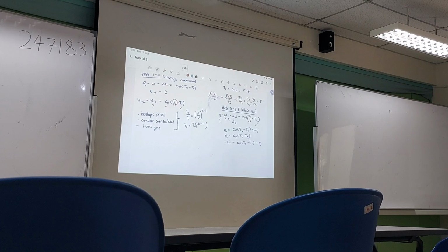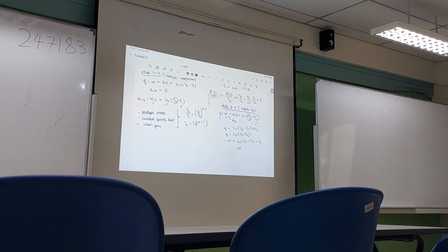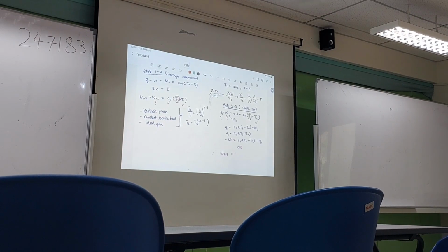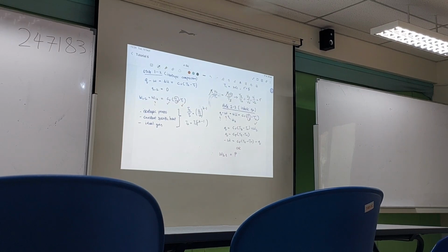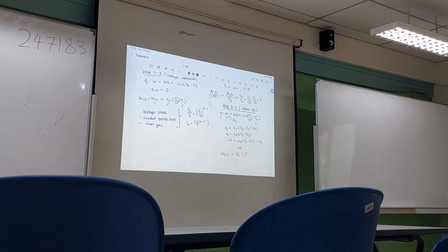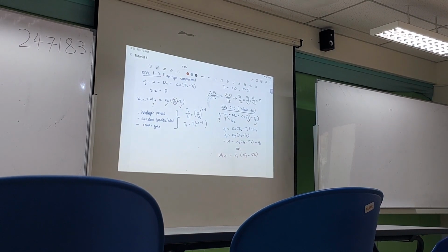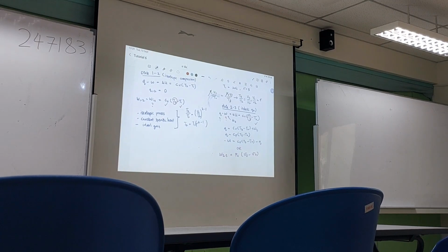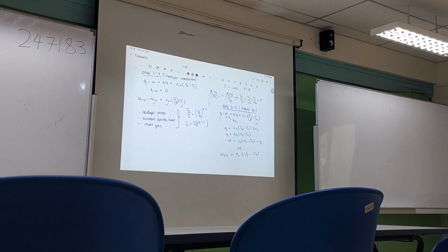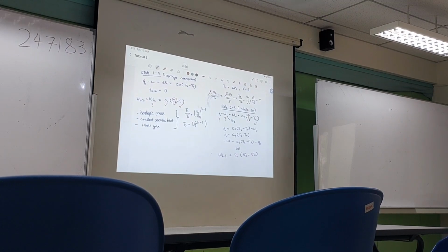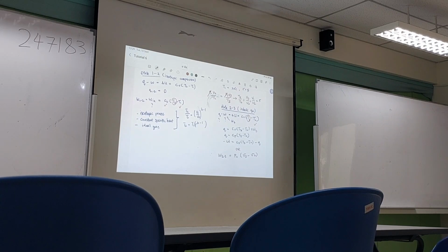We know that this is a constant pressure process, right? So a constant pressure boundary work process, which means that work 2-3 is actually equal to the boundary work, which is P(V3 minus V2). So this is the boundary work done. And you know that it should be work out, because Q is in. Q is in, then work definitely has to be out. But of course here we still cannot solve this, because we don't have the actual value for the specific volume. We only have the ratio.